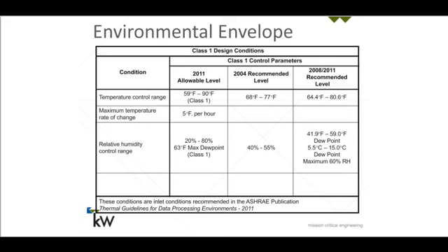As we said, Julius covered this one very well. Clearly, we have an extended range for supply air inlet into the IT equipment. And obviously, if you're able to operate your IT equipment at those elevated temperatures, we can take advantage of significantly more hours outside for free cooling.